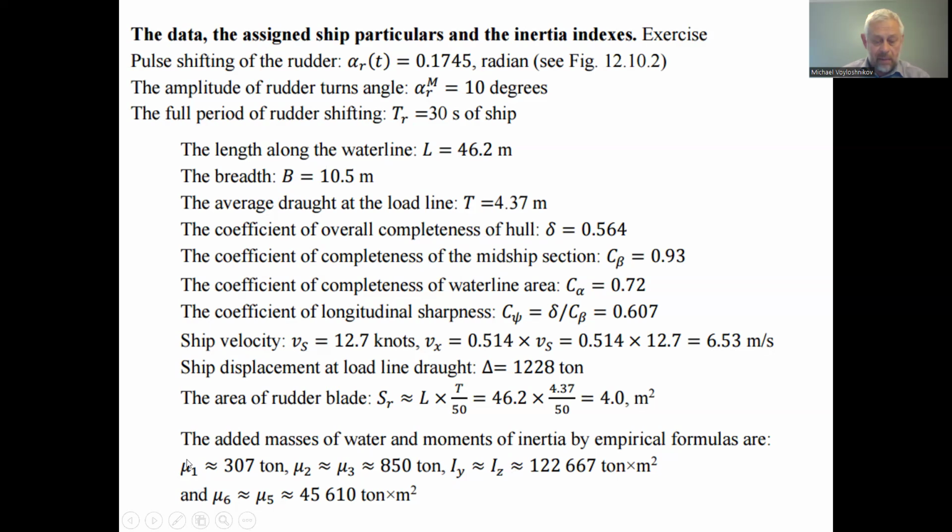And this is the impact of the water inertia onto the ship motion with acceleration along the longitudinal axis associated with the ship axis X. And these are the added masses for the ship translational motion with acceleration along the transverse axis Y, ordinata, and Z. Z is the applicata axis. For the translational motion, the added characteristic of the water inertia is 850 tons, which we got in the previous article 12.9.